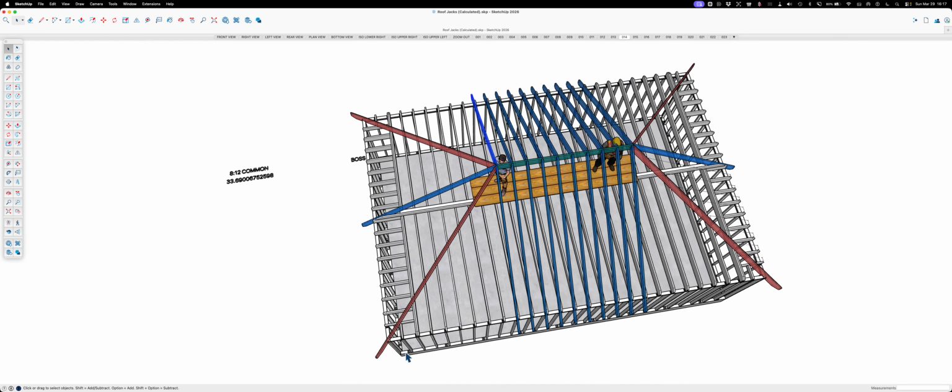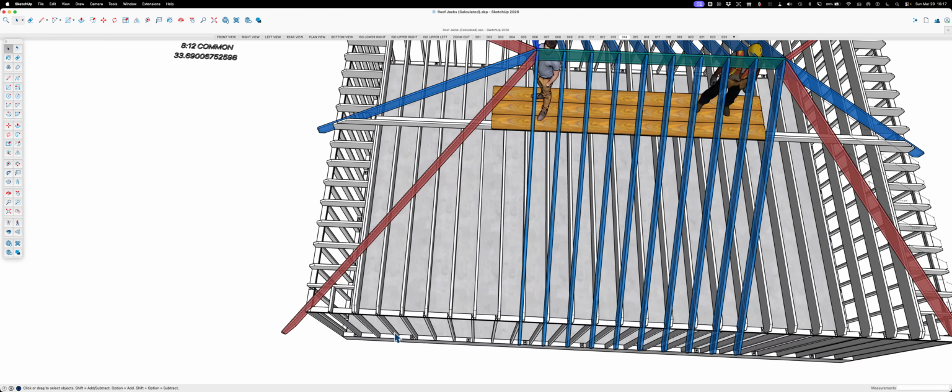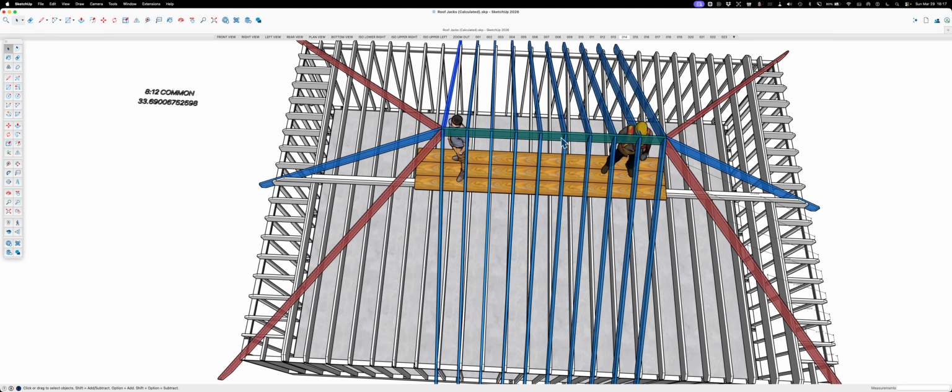So I guess I should step back and say, make sure that whoever does your foundation follows the plans, and make sure that whoever frames your walls, if that's your crew, makes your wall spans exactly what the plan is. And then you could pre-cut this roof a week ahead of the project. If you know your crew can hit it, imagine showing up and all this stuff is cut and labeled. And since this is the only ridge out here, this would be Ridge A, and everything would just be so easy to put up. It'd be so fast.